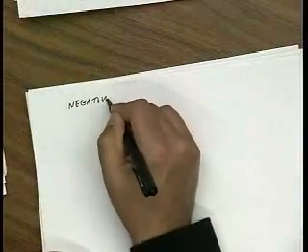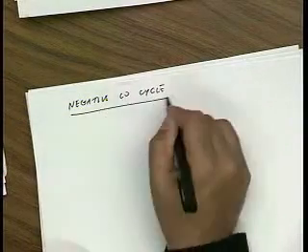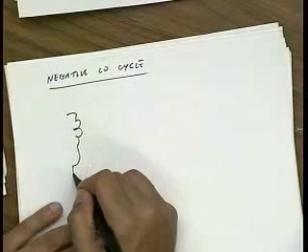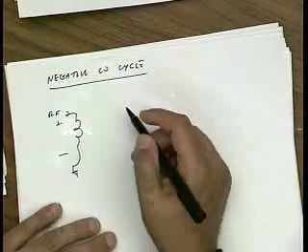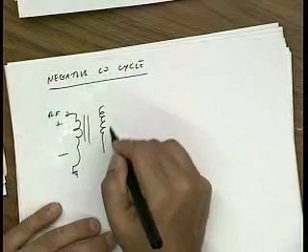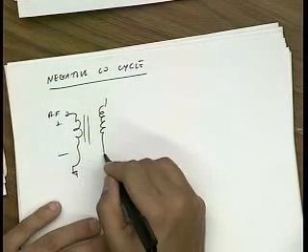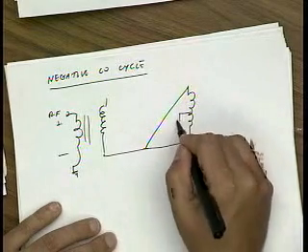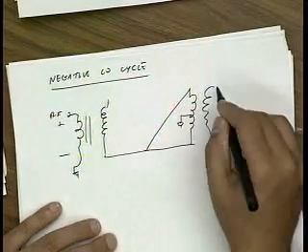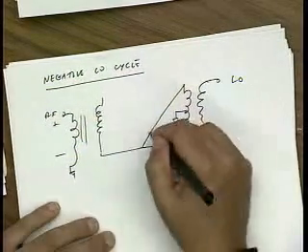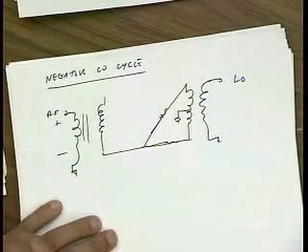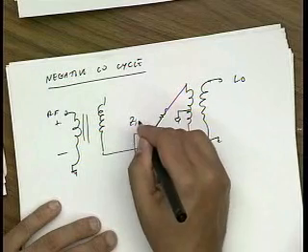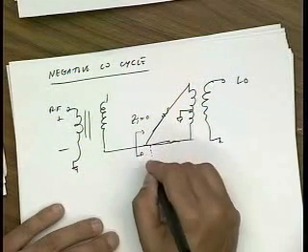Now for the negative LO cycle, it's very similar. Again, I have my RF. Now D1 and D2 are off, and D3 and D4 are on. And the circuit looks like this. This is my LO. Again, this is the on resistance of D3 and D4, if you like. Again, looking into here, I see practically 0 impedance. I replace it with a virtual ground.